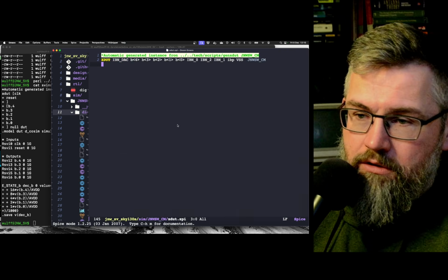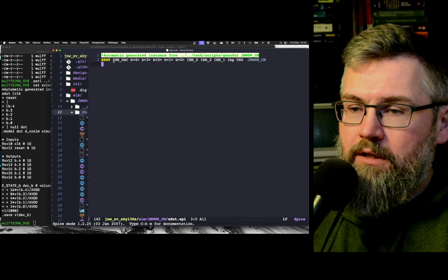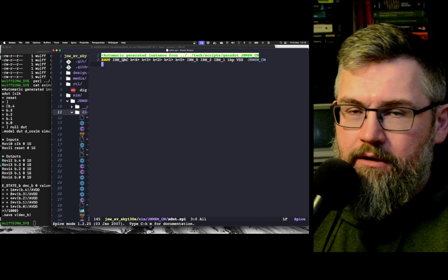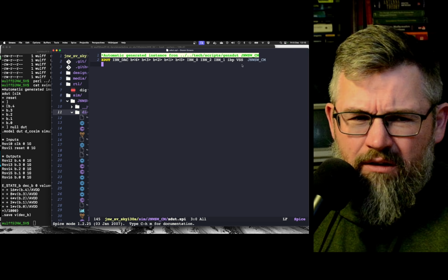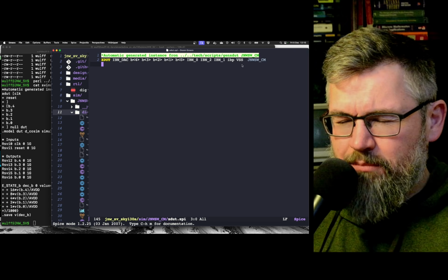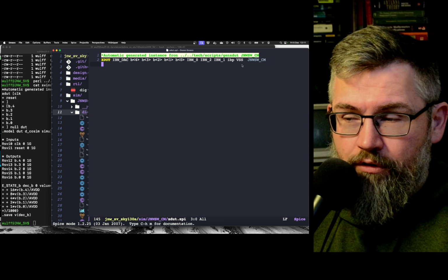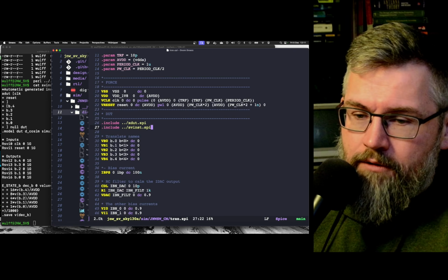So let's open that, just have a look. So this is also a generated file that gives me the instance of the XGAM schematic. So I use this kind of thing because I don't want to write this manually, because if I change a port in XGAM, or if I remove a port and I forget to update the instance, then my simulation doesn't work and so on.